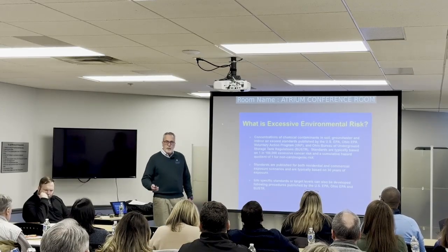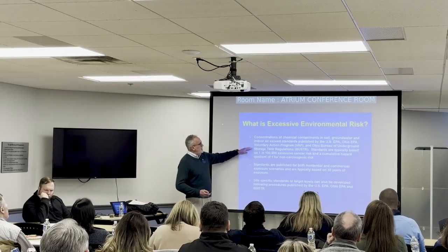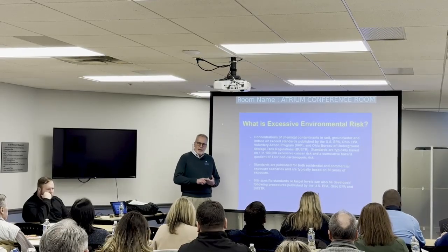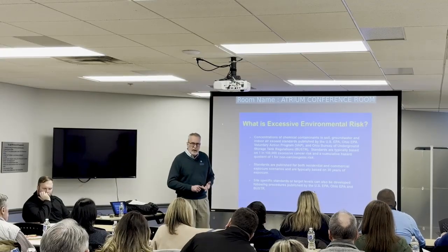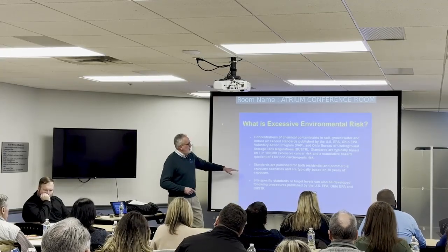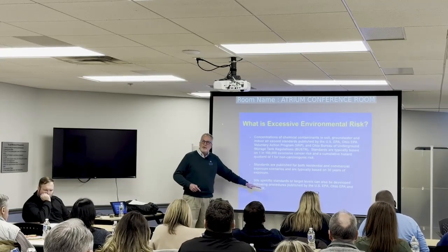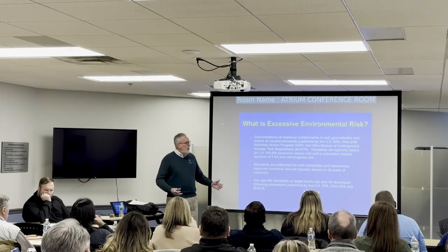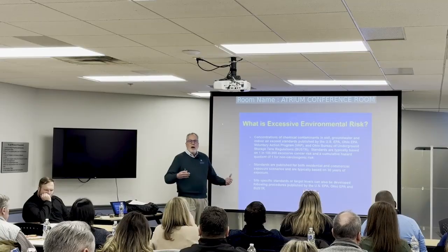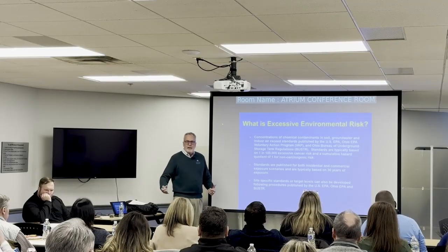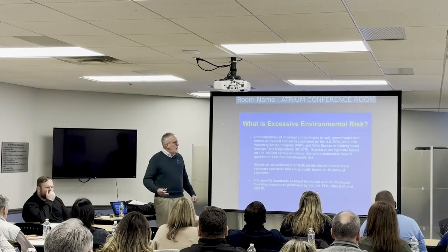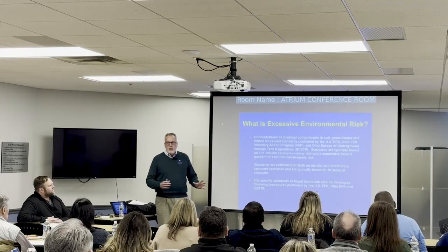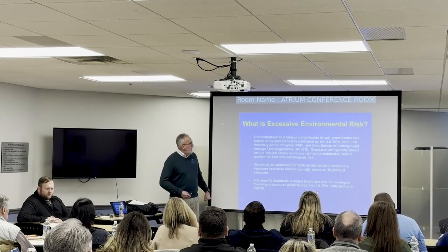What's excessive environmental risk? We all have these standards: Voluntary Action Program, Ohio EPA, we use those a lot. There are generic soil direct contact standards, and there are indoor air standards. They're based on commercial and residential scenarios. Both of them are based on about 30 years of exposure. Obviously, the residential scenario involves longer duration at home and impact to children, which is a different scenario, and that's why your residential cleanup numbers are always going to be lower than the commercial numbers.